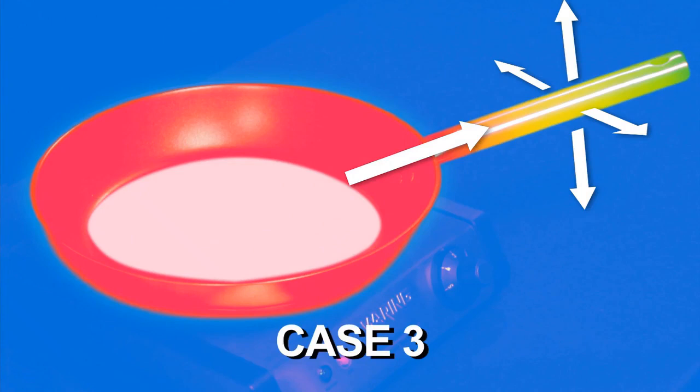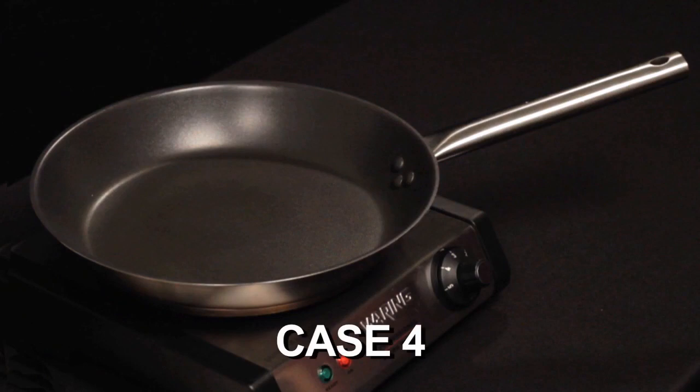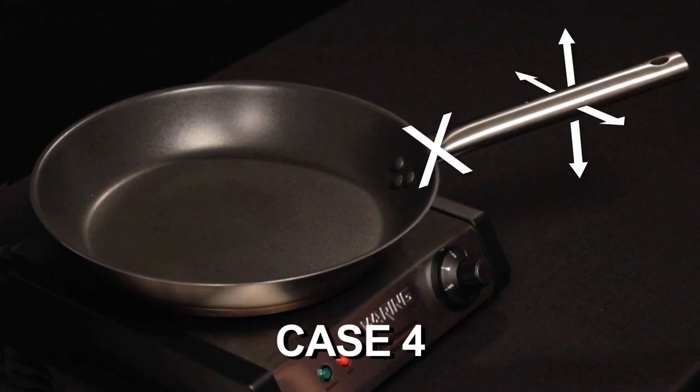In case 3, we went back to our assumption of perfect thermal contact between the pan and the handle, but we allowed for some heat transfer from the handle to the room. For this final case, let's pick and choose the most reasonable assumptions from our previous cases and build from there. We'll assume that the handle can exchange heat with the room. We'll also assume that the pan and the handle are insulated from each other. This is reasonable because if you're a pan designer, you don't want your customers burning their hands. But of course, there is no such thing as perfect insulation, so we'll have to allow for at least some heat transfer between the pan and handle.